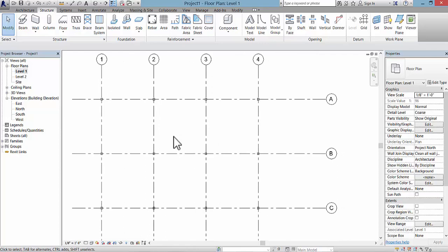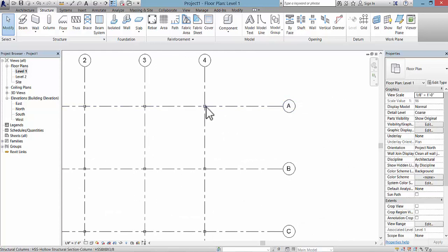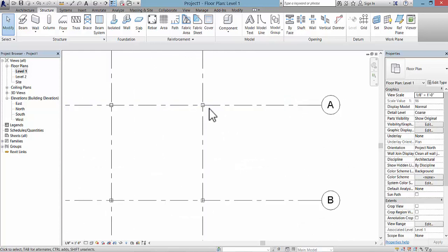or whatever we're going to use for the structure around it. The structure itself is away from the column. So the project that I'm working with, as an example, has 11 inches between the column center and where the precast concrete panels start, the 6-inch panels.